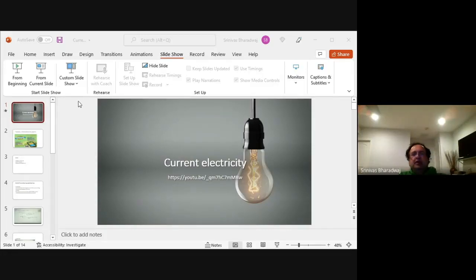Let us say you choose the current in this to be I1, that is also this one, right? So if you say it is going up this way, it will be coming down that way. So if this is I1, this is also I1. So then this is I2. So now when you do one loop, you then have I2 minus I1 is this current, right? And therefore, you can calculate that current. And therefore, from that, you can then calculate the whole loop.